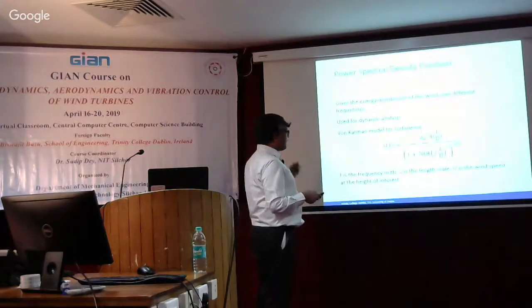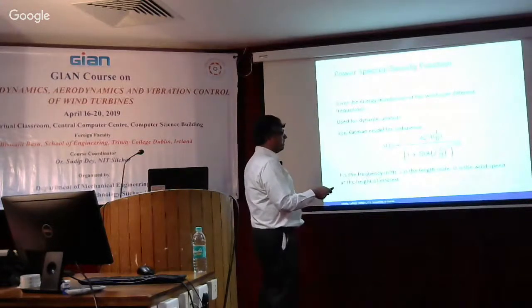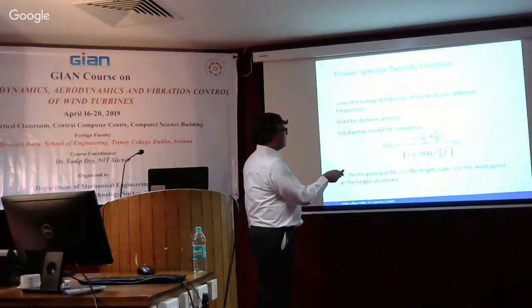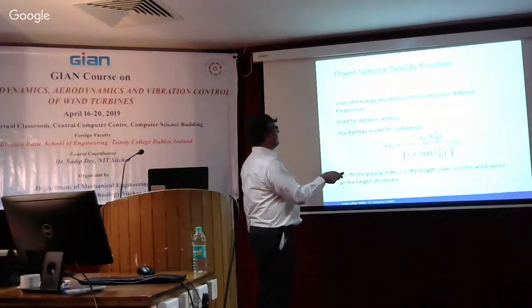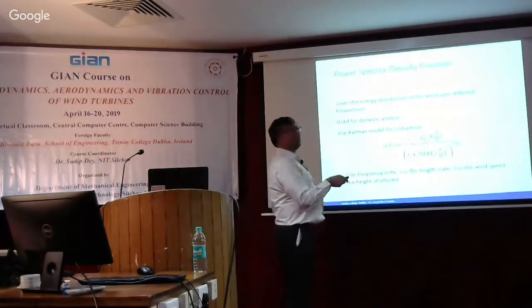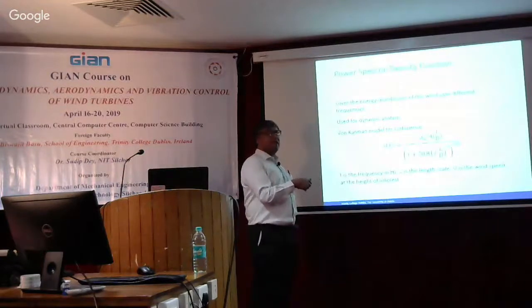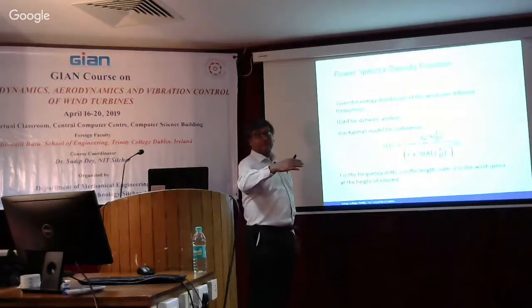It's interesting to point out that if you look at this structure, you have a power of 5/6, and you have a square term here. So if you multiply it by 2, you have 5/3. And because you're in the denominator, take it to the numerator, you have minus 5/3. So this is basically following Kolmogorov's minus 5/3 decay of turbulence.